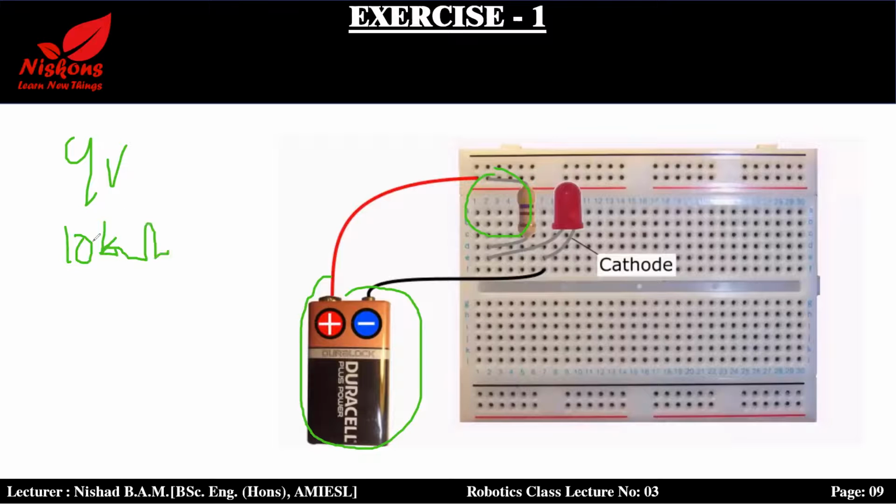Inside the Arduino box, you have this resistor, right? You have to obtain a jumper cable and connect it here, then connect the resistor, and after that connect an LED bulb likewise. What you have to do is turn on your LED bulb. This is your first task, exercise 1.